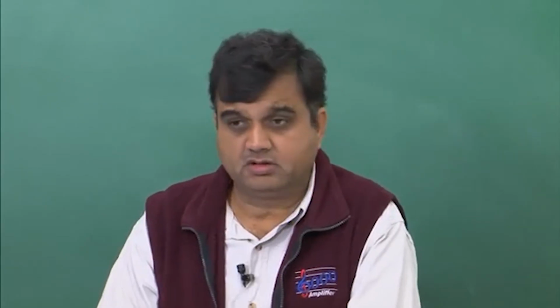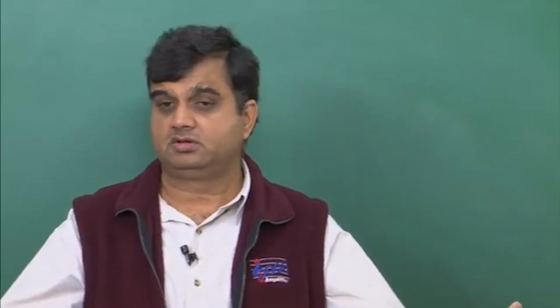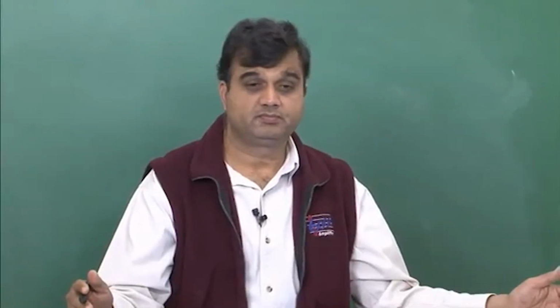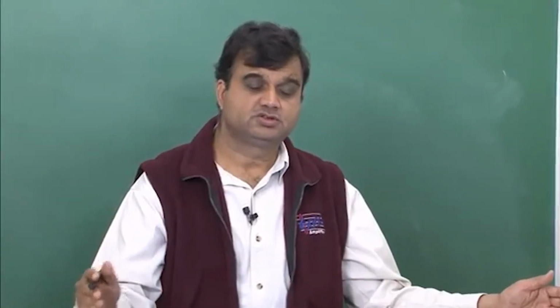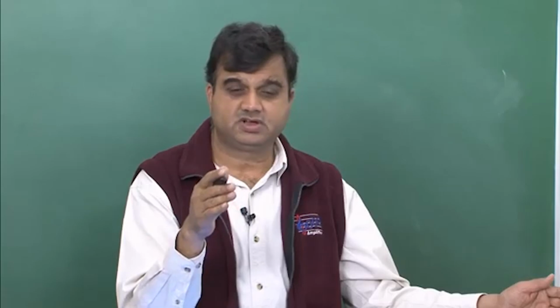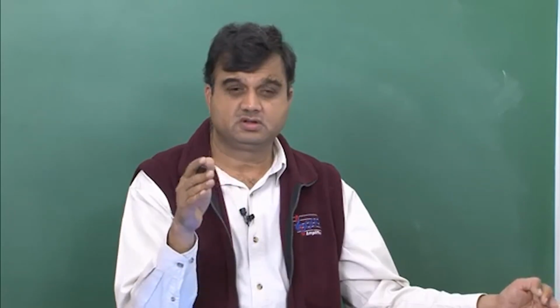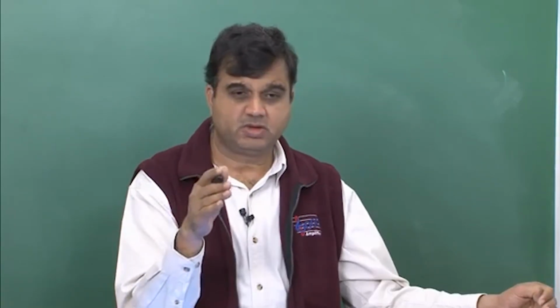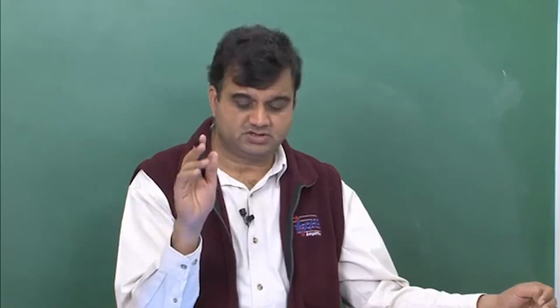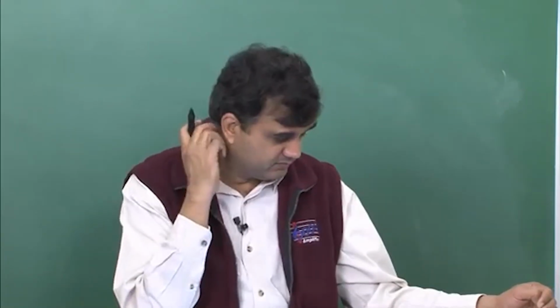So, what does that mean? Our sampling frequency was 8 hertz. So, the maximum possible frequency which we can extract out of it was 4 hertz. Maximum possible frequency was 4 hertz. So, that is one thing.